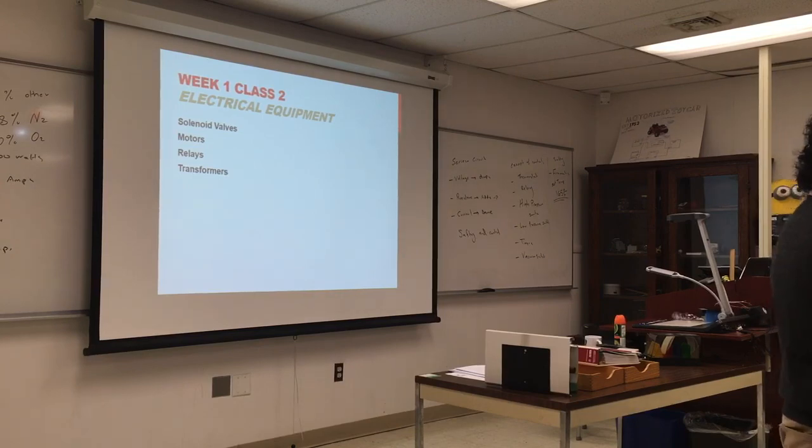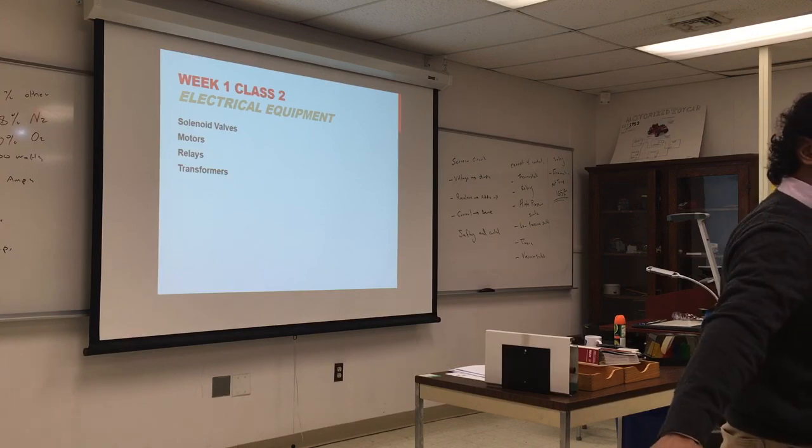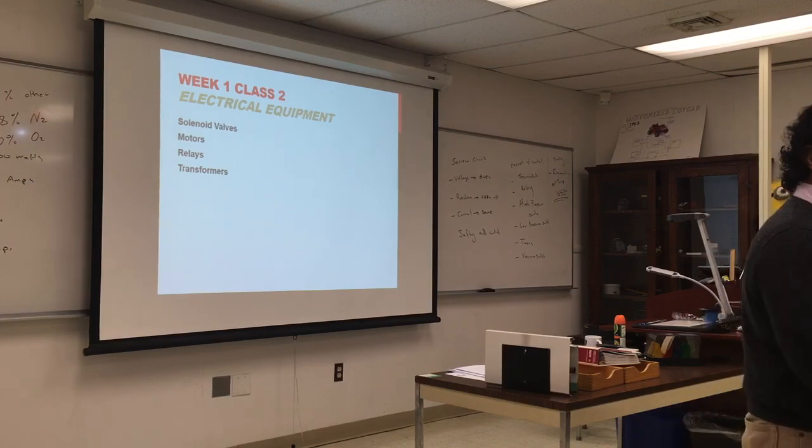There's another one here. Once the water is between the limits, it will turn on the pump. So one turns on the burner motor, because we need more heat. And the other one, when the heat is satisfied, circulates the water. So we have two logics in this aquastat.